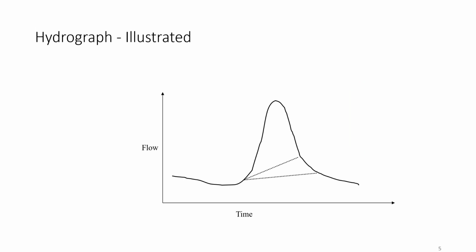One of the main purposes of a rainfall runoff model is to produce a hydrograph at a specified location. A hydrograph is simply a plot of discharge versus time for a given location. The term hydrograph is often synonymous with the term discharge, and you might hear these interchangeably. The excess rainfall transformed to runoff makes up a part of the total hydrograph, which we call direct runoff. Interflow and baseflow, which deals with the subsurface movement of water, are also important components to the total hydrograph.